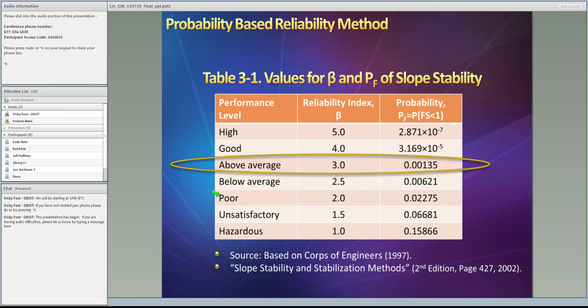So the flowchart of the Monte Carlo method for the geoshaft system would be, first, collecting data. Second, we choose the target reliability index equal to 3. And then we select different shaft locations as well as different spacing and diameter. Then we calculate the factor of safety based on the limit equilibrium method and arching theory. After that, we run a Monte Carlo calculation for the total number of random samples. And finally, we get the reliability index beta.